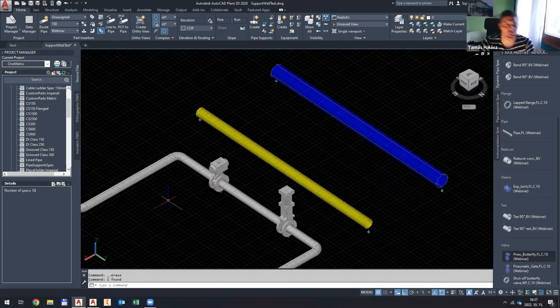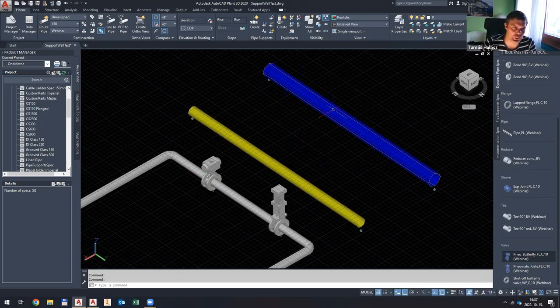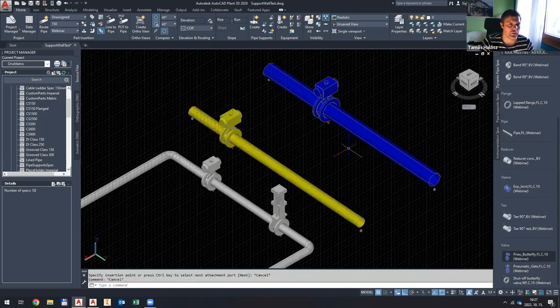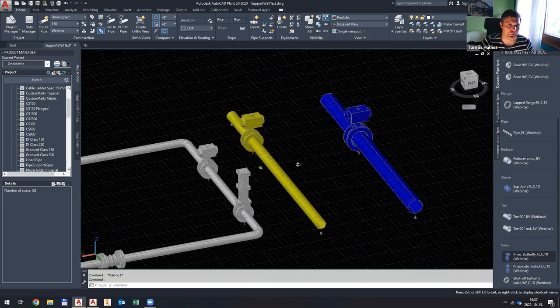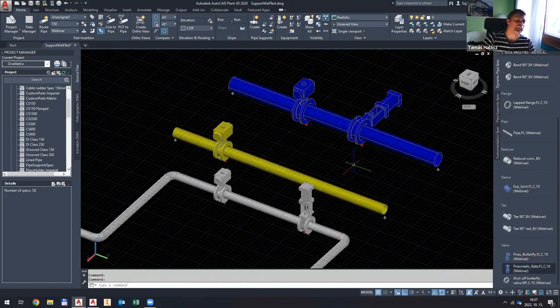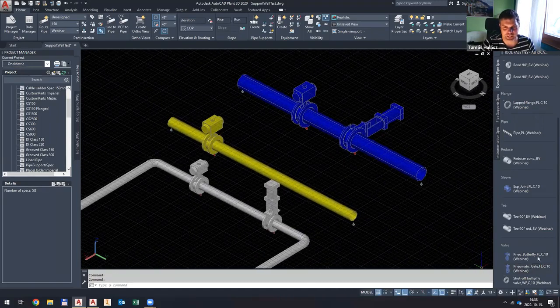Okay, yeah. So it is different colors, and if you have a STEP file, even if you convert it to a valve or a Plant 3D object, it will not work with this color coding, but these kinds of scripts are working. If I enter this valve, it is blue as well. So it is completely working like the inbuilt stuff. Okay, it is not really beneficial for the end product, which is the 2D drawings, but I think it's also nice to look at in the 3D model.